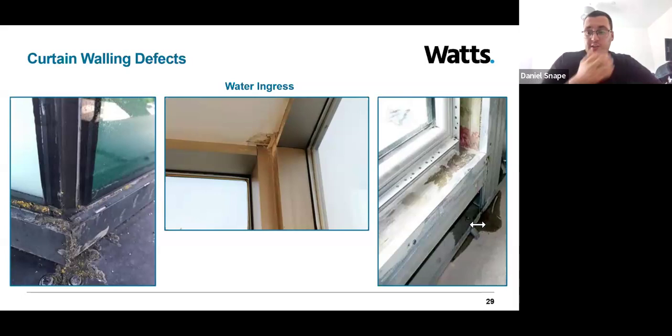But what I'm trying to get across is that leaks may not be seen right away, as the lining of this system may conceal the severity of the leak. That can result in increased damage and cost to repair. So it's really important when this system is installed that someone is reviewing the process and making sure that it's being installed correctly and that it's sealed. Yes, unitized curtain walling systems are put together off-site and then put in place, but often they may need to be sealed at the joints with a mastic, and if that's not done correctly, then water can get through the system.